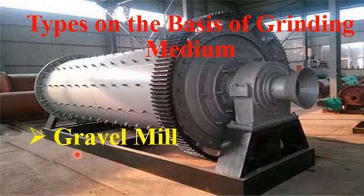Okay, the first type of the ball mill apparatus based on grinding medium is a steel ball mill. The second type of the ball mill apparatus is the rod mill, and the third type of ball mill apparatus based on a grinding medium is a gravel mill, which uses gravel and pebble for crushing and converting a bulk material into a very fine material. And this type of mill is most common in the granite and cement industry. Okay,